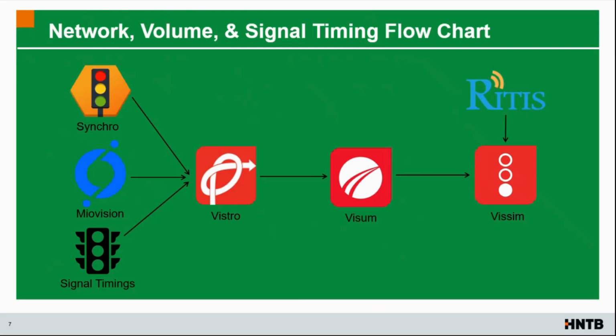So an existing Synchro network was provided by the client with partial geometry developed, but this was an older, outdated model, so we needed to further develop it and also make some changes for the current geometry. So we brought that into Synchro, and then we developed that, and then Miovision took counts for a 2-day period and collected raw counts for us to use to determine the peak hours, which were determined as 7:30 to 8:30 a.m. and 4 to 5 p.m.